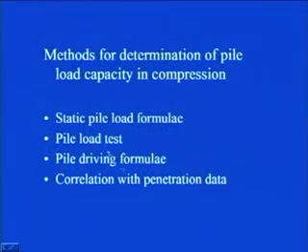There are various methods from where this pile load carrying capacity in compression can be estimated. Usually they are grouped in 4 categories. You can find out the load capacity of pile in compression by static pile load formulae. There are various formulae for different types of soils.